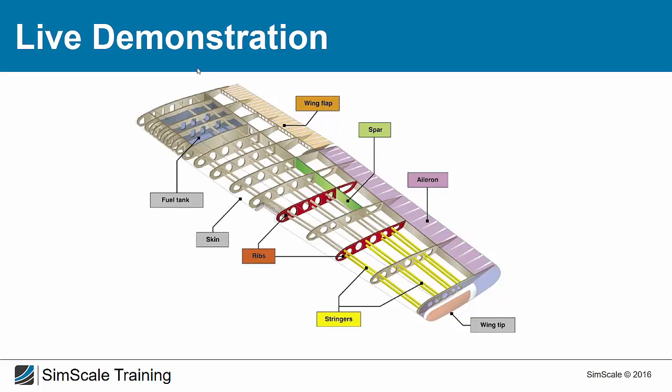And so the main challenge when it comes to the mechanical design of these aircraft is really to make sure that you are as light as possible. Therefore, this kind of design structure is used in, I would say, every modern airplane in the world to make sure that you have maximum stiffness and minimum weight. So the idea is you use ribs. And these ribs in the end are connected by stringers.